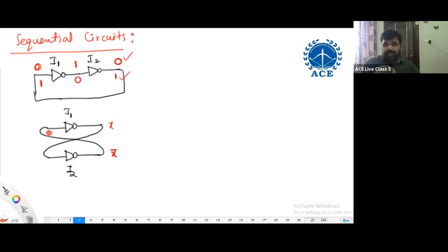So there it is not only oscillator. Oscillator is one part, but we have other parts to control all other parameters like jitter and skew and so on. So locking time, how much time it is taking to lock, even though there is disturbance, the disturbance again must be settled.